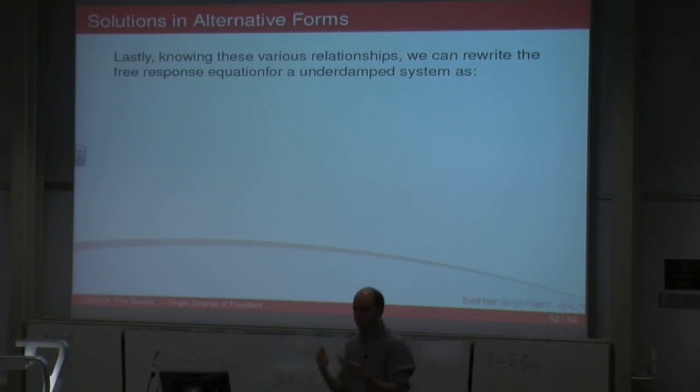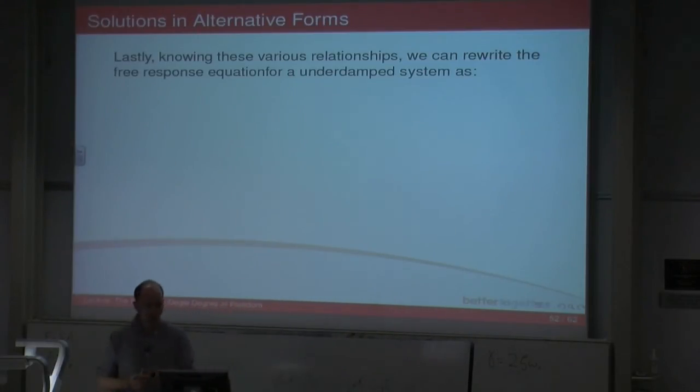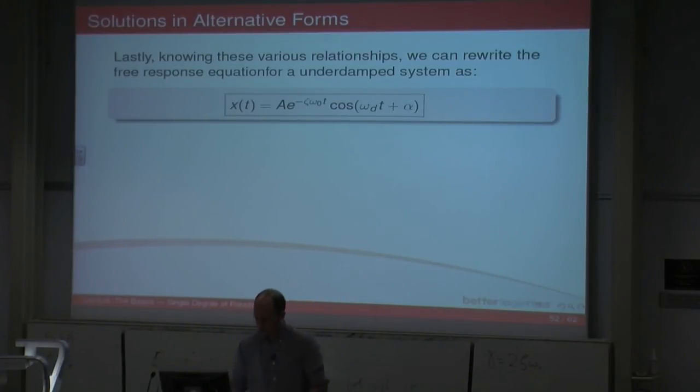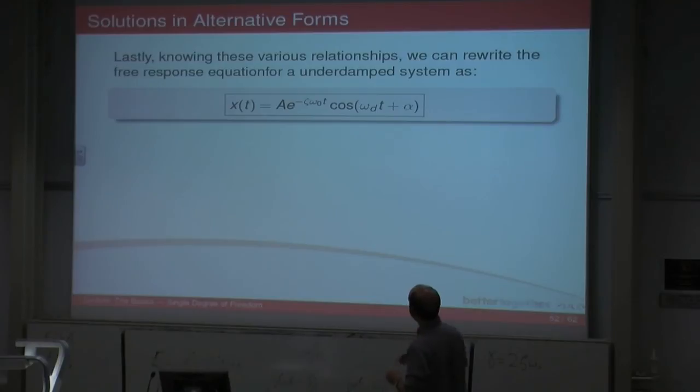Now, knowing those various different forms, things like damping ratio, amplitude ratio, frequency ratio, we can redefine some of those equations that we saw in terms of those terms. And sometimes, like I said, and we'll come across this in one of the examples I'm going to do, it often helps to use these alternative forms. And so let's go through some. Underdamped system. Okay, so this is a free damping. So we're not driving it. We had this equation. But we didn't have it in this form. We had a gamma upon 2 term, okay, where the zeta is.